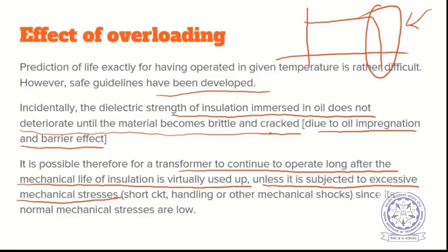They will happen during short circuit or even handling of the transformer. Suppose you are shifting the transformer from one place to another, but of course it is not possible to shift a power transformer. I am talking about distribution transformers. So while handling also there may be some damage or any other mechanical shock. There may be the insulation which is already brittle might have succumbed to that.